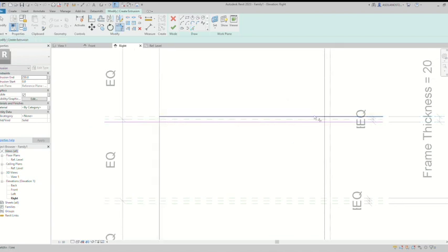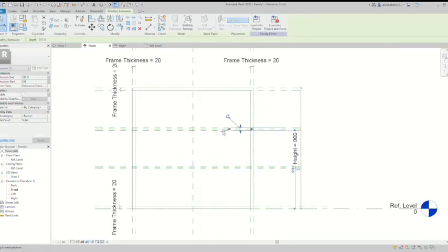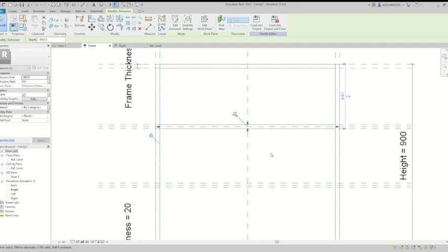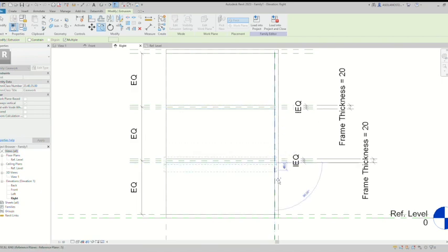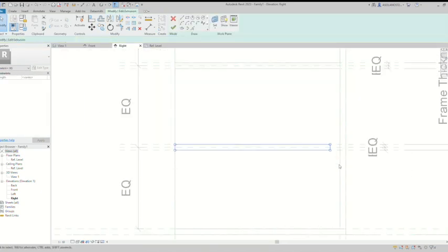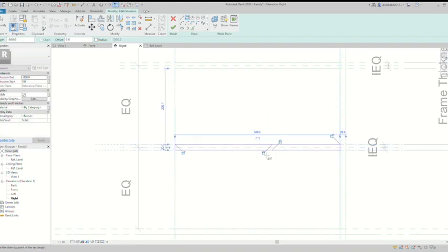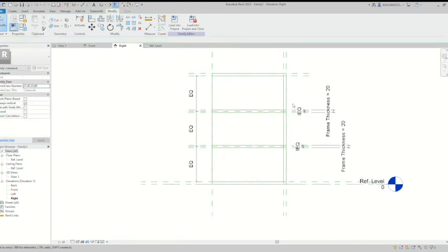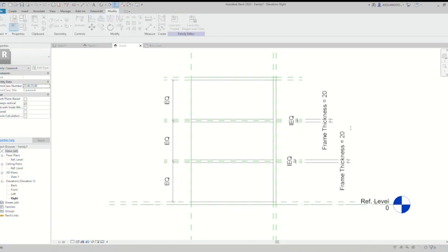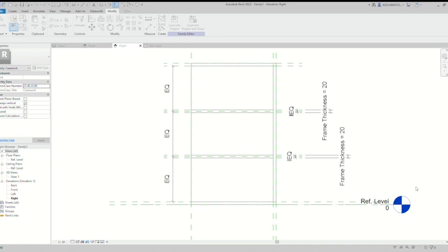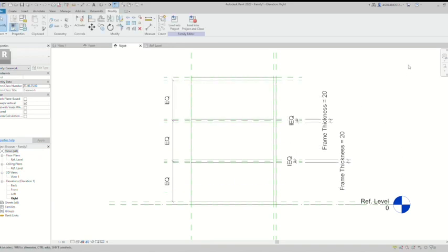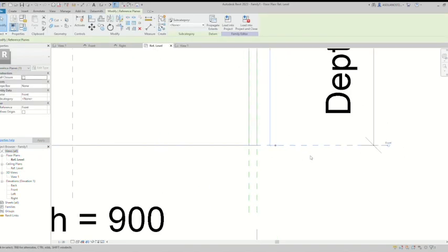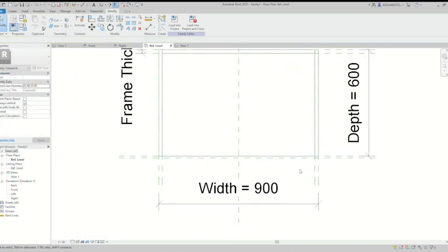Once we have finished making the reference planes and every parameter, we can now make the extrusion and lock it with the reference plane that we made previously. Because in this case I want to create a similar panel, we can duplicate it for the lower shelf, just making sure that the extrusion and the lines that create it are locked with the reference plane that we made.